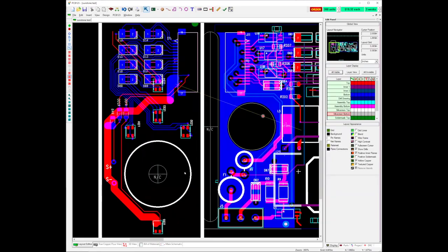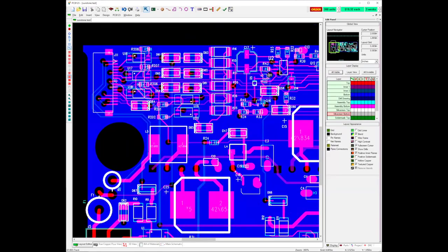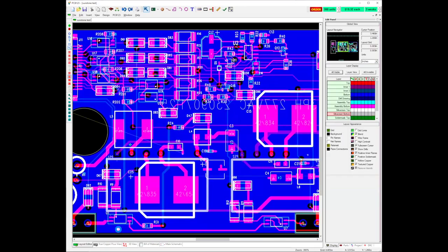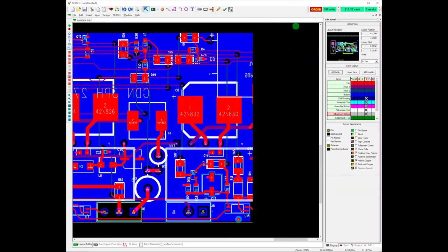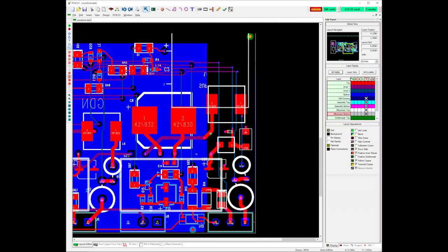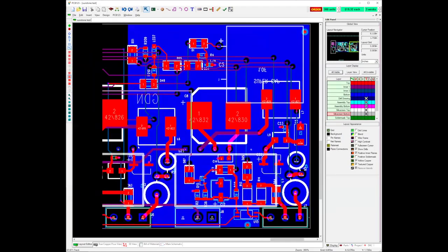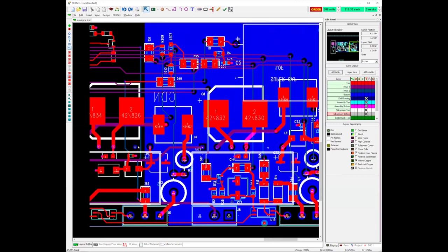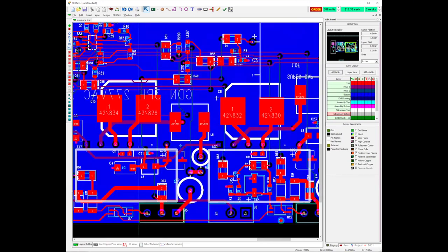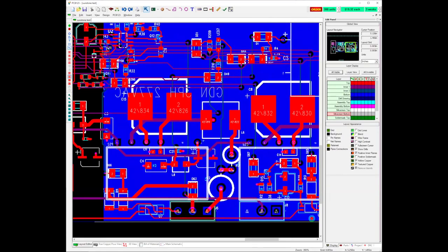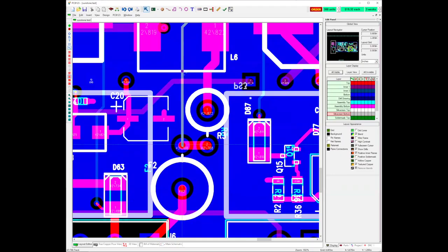And worse is if I've got a net that carries a lot of current and I accidentally do that, change net width, and it's got other instances of that net somewhere else on the board, it can create a narrow wire that burns out, just flat won't carry the current you're hoping to carry. Like is present here between these two pins. I've got a nice fat wire and a nice skinny one. And this skinny one's just a sense wire, so it doesn't have to carry any current.